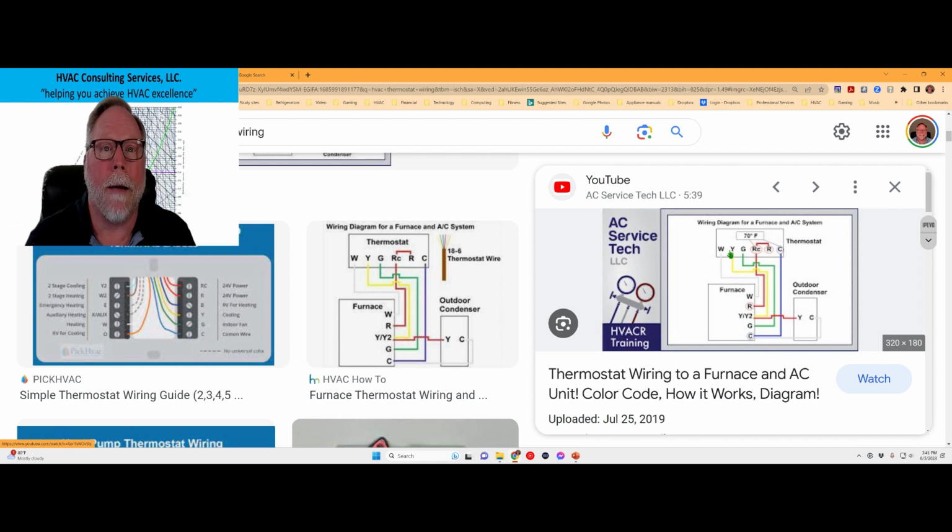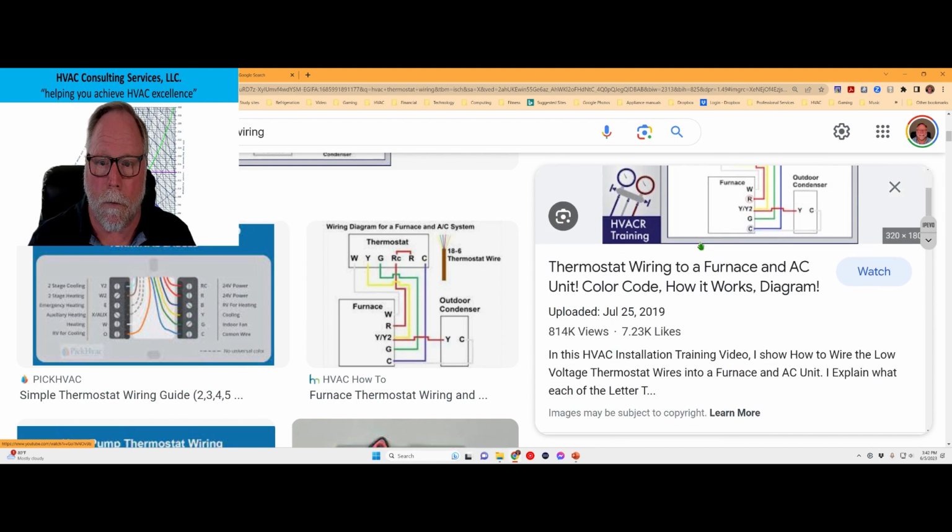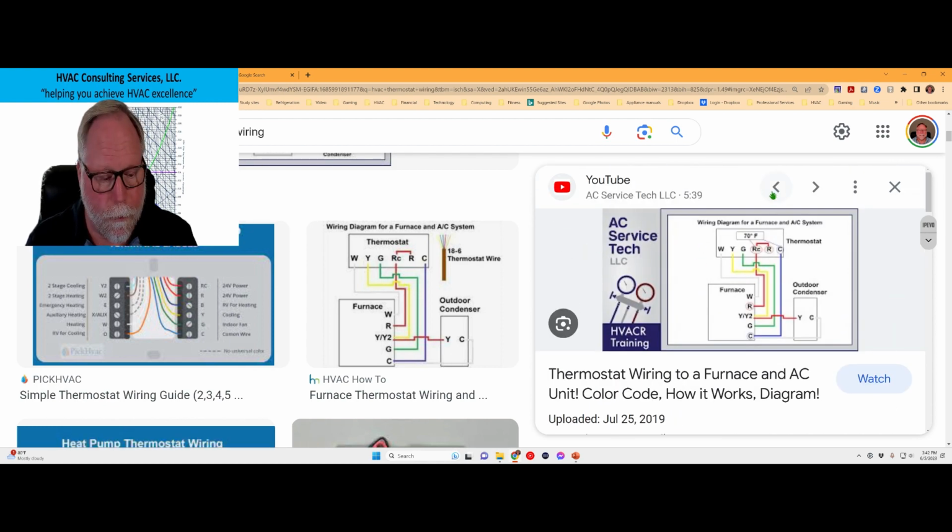Right? Clear as mud, right? So if a thermostat has Y1 and a Y2/Y, then if you have a single stage unit hooked to that thermostat, the cooling call is going to be out on that Y/Y2. If it's a two-stage unit outdoors, then Y1 is first stage, Y/Y2 is second. That's why they broke it up. Okay? Now, let's go back.